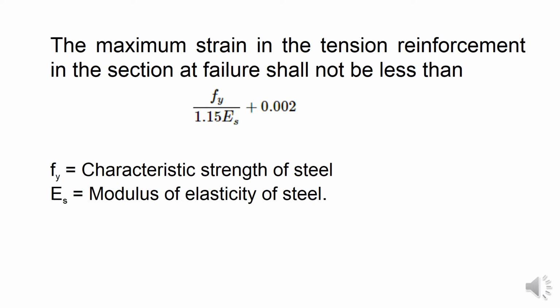So if fy is the yield stress, we have to consider fy by 1.15. For design purposes we never take the ultimate limit for our design calculation.